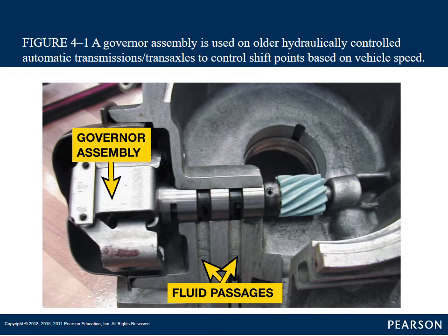And there's a valve inside that governor. And there on the left, those arms, or whatever you might want to call them, weights on the outside, actually, as it spins, will flex outward. There's tangs on the inside of that then push down on a valve and allow fluid pressure to move.